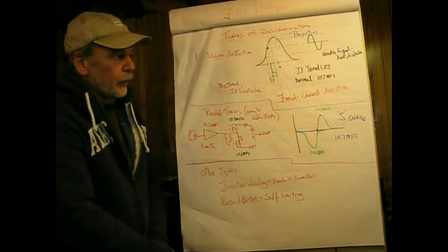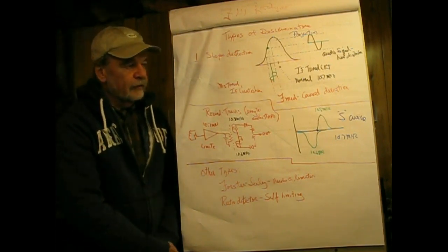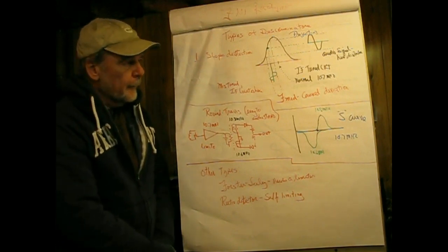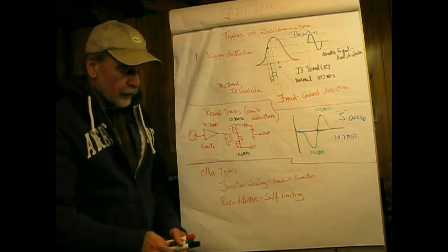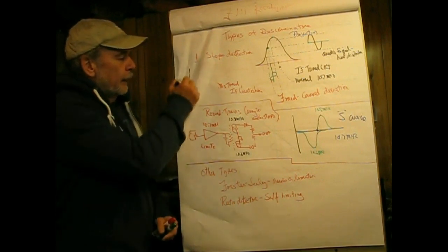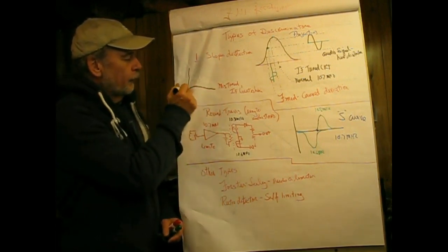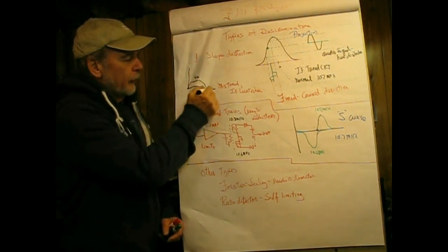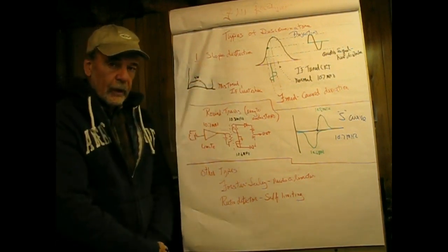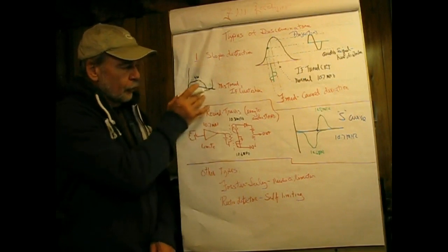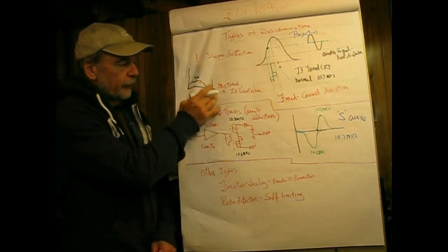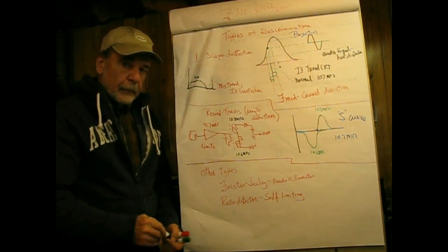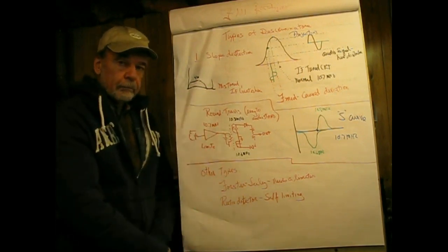So in the end of the 30s, they actually were selling television sets, and there were very few transmitters around, and the television sets basically had, from the standpoint of video, about 4 megahertz, and then sitting outside of that was a separate transmitter. So this would be the video information, and this would be the audio information, and that was an amplitude modulated sound system.